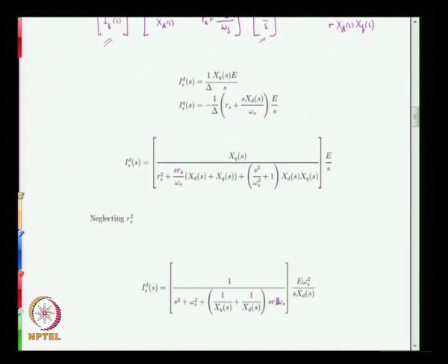So Ra into omega s, Rs square is of course neglected, so that you get this omega s square, what you have seen in the denominator here now comes over to the numerator, so E omega s squared, and since we have taken xd xq outside, xq is removed, so what you are left with is xd of s.